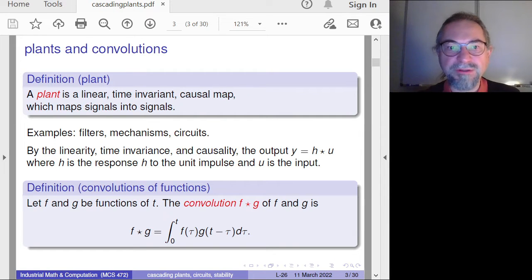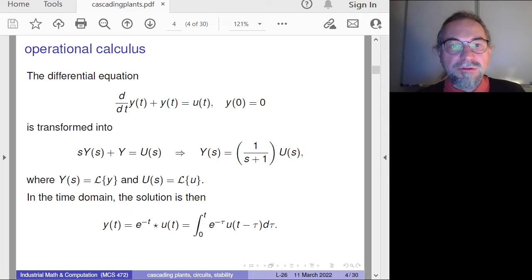We defined this earlier for discrete signals. Lately, in the previous lecture, we generalized this convolution operator as an integral operator. So we can speak of the convolution of two signals. And the little h will give rise to the capital H, which is then the transfer function. Okay, so we have covered the Laplace transform.